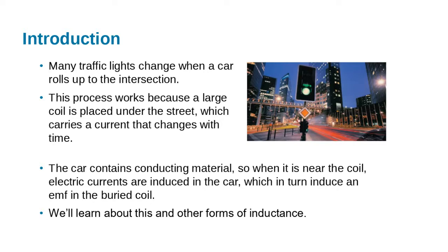But I think also in this country there's a few of these inductive sensors at traffic lights. There's just a large coil under the road that's got an alternating current in it, and because the car is made of a conducting material, when it's near the coil, you actually get electric currents induced in the car, and those in turn induce an EMF in that buried coil, which can then be picked up and used to determine whether there's a car there or not.